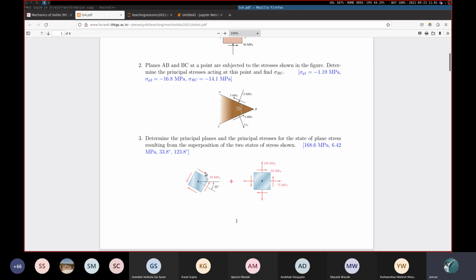No, if you're just saying that, I'll just rotate it by like whatever 60 degrees or something, that won't do anything. Okay, sir. When you rotate a stress element, correspondingly you have to use the stress transformation equations to obtain the stresses that would appear on those vertical and horizontal edges after rotation. Otherwise, you are just rotating your computer. Okay, sir.